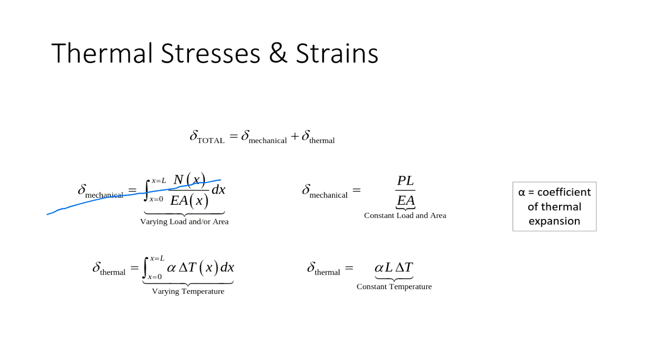Instead of a pull load at the end, it's like a distributed load. Actually, the way I'm holding this I-beam right now, this is not a constant load. This is a distributed load, because as the I-beam gets longer, it gets heavier. So I'd have to integrate that as well. Now, that's mechanical load. That's actually taking an element and loading it, pushing on it or pulling it. What about thermal effects?